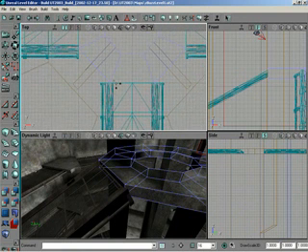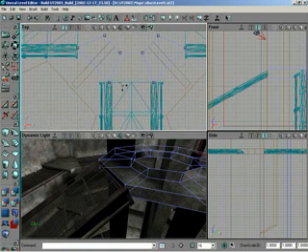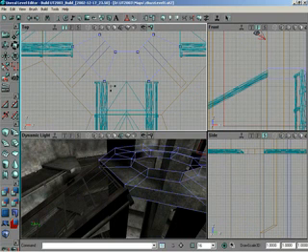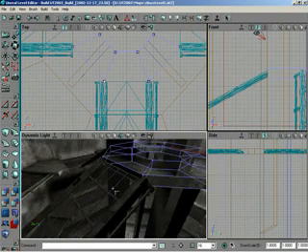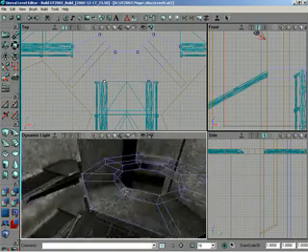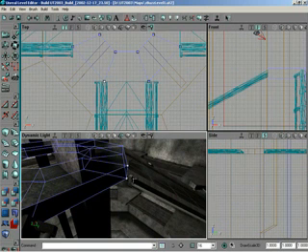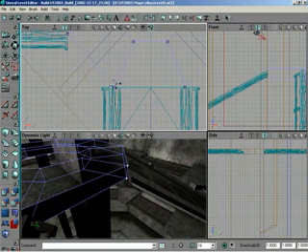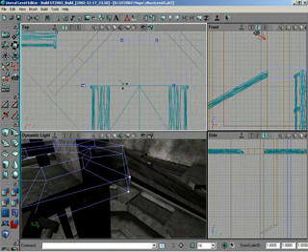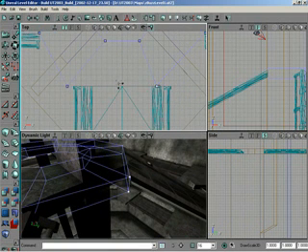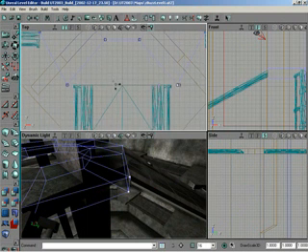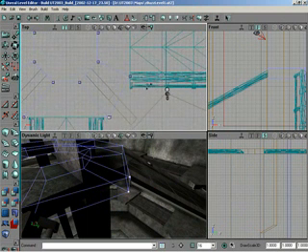And then, let's see, what does large vertices look like? That might help. So I'm going to just use Control-Alt and select these 2. You notice if I move my perspective around, there, you can see I have both of those vertices selected. So now I can Control-drag those out. I might drag it a unit past where those are. Yeah, it looks good. And do the same for the other side, Control-Alt, and then I can Control-drag out. And continuing on for the remaining 3 sides.